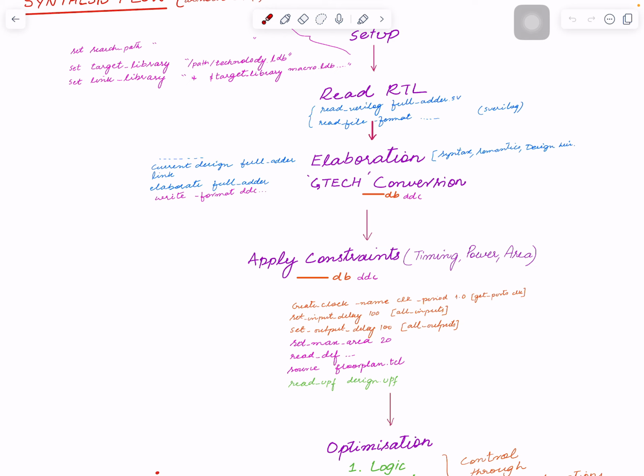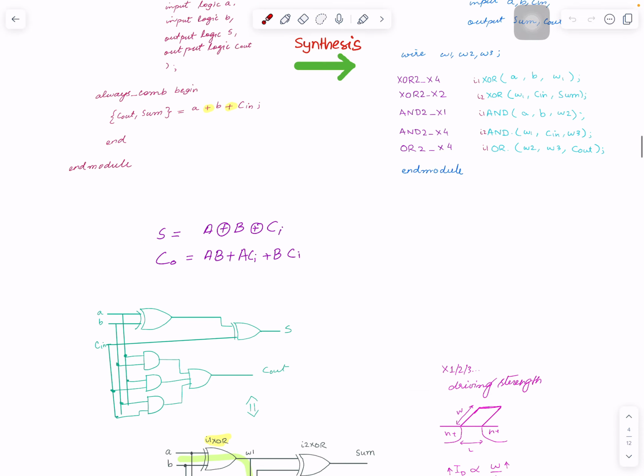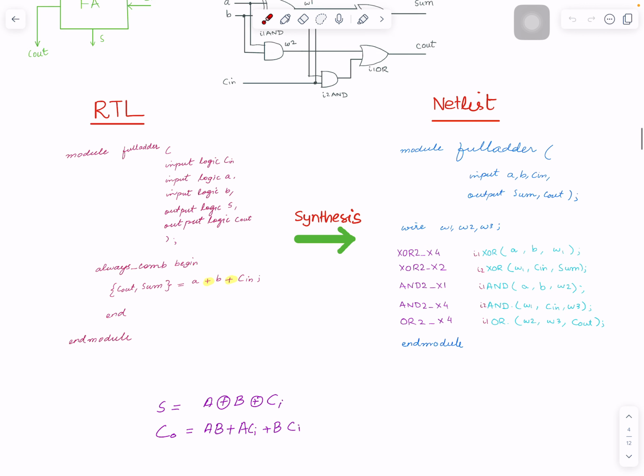So the basic timing constraint is your clock, because we time everything with respect to clock edges. The time between two positive edges, or between positive and negative, rising or falling edge, and all that, is a very important constraint. In our design right now, the SystemVerilog file that we did, there is no flip-flop. I'll put a flip-flop in, but right now there is no clock constraint. So even if you provide a clock, it doesn't exist.